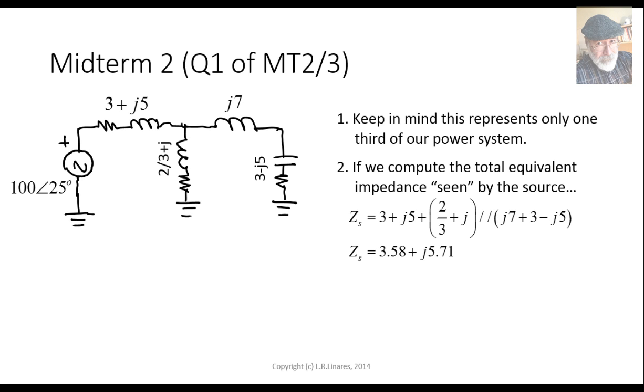And that is the power, 1/3 of the total three-phase power of the source. Let's do that. 100 squared, the RMS volts squared, divided by the conjugate of the impedance. What is missing there? Times 3, right? To account for the power in the other two phases. We do the math and we say that source is delivering...